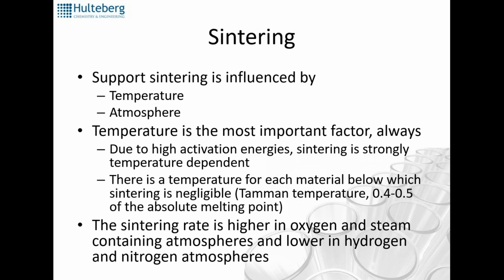But if you have the same temperature, you will see higher sintering rates, most likely when you have oxygen and steam present, because those promote the sintering reactions. You will, on the other hand, see less sintering if you have hydrogen and nitrogen present.